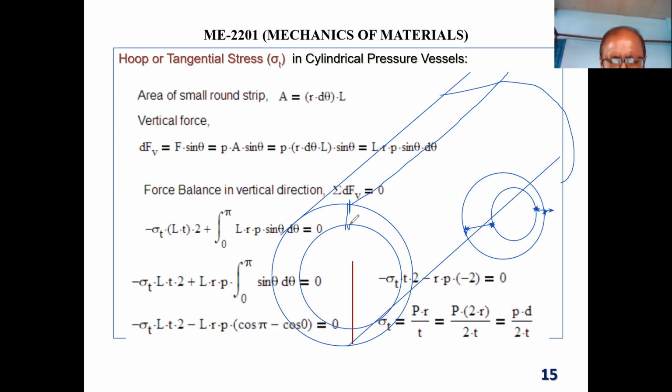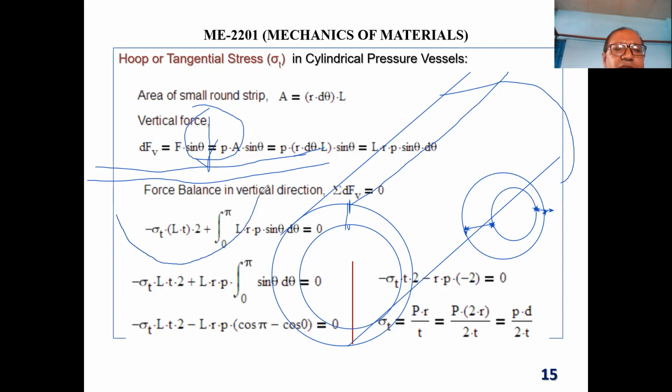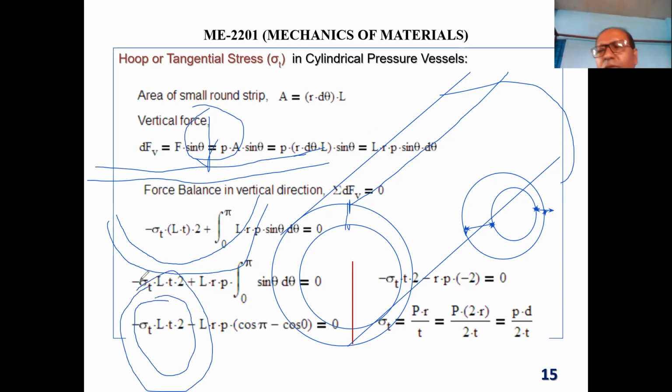So how do they normally make it? They take a sheet metal sheet, then they roll it in a machine with a roller, and obviously you have to apply some pressure, and you roll it down. Then this flat plate gradually converts into a round shape, and finally it becomes completely round. Okay, then you can do the edge, you can do the welding.